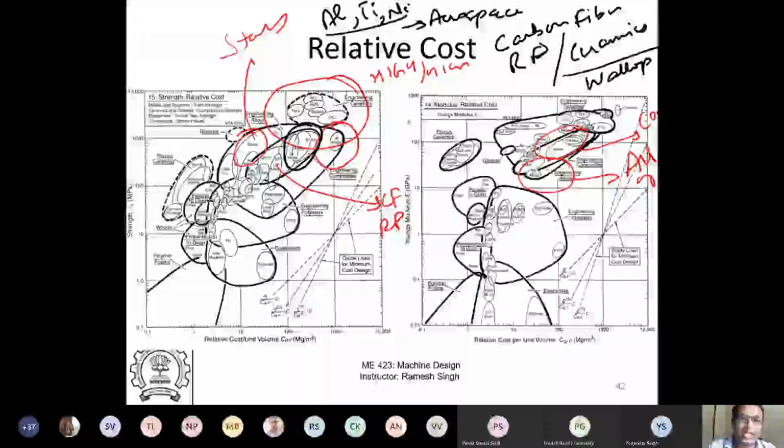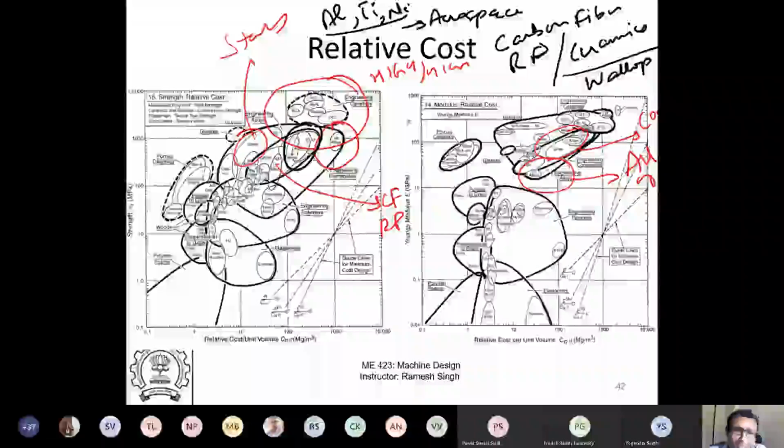But if you're making it for mass production, aluminum, titanium, and nickel have to be used with caution. There has to be a functional requirement where you justify the cost. So carbon fiber is expensive, and tungsten alloys, or pure tungsten, are also very expensive. So it has to have some key applications there. And all these have reasonable strength and also Young's modulus.